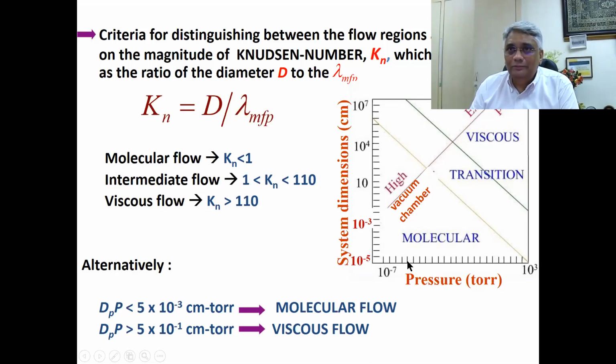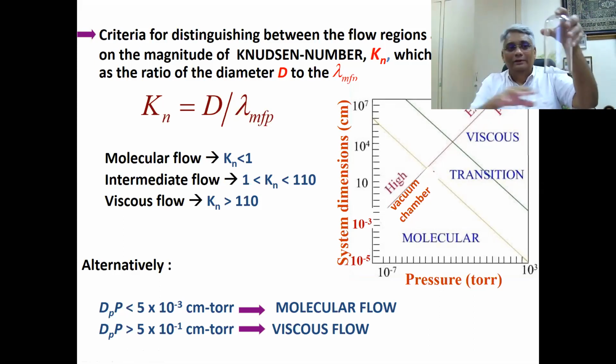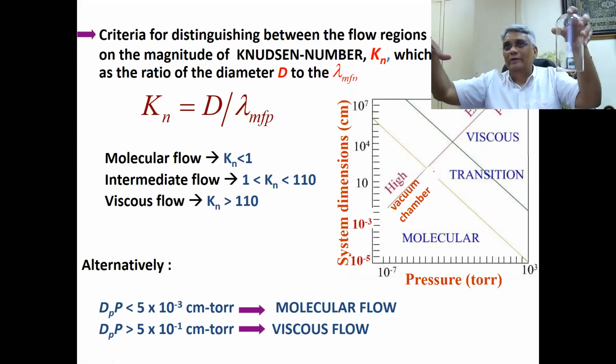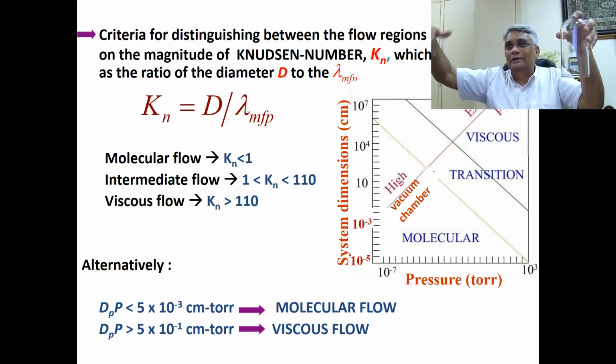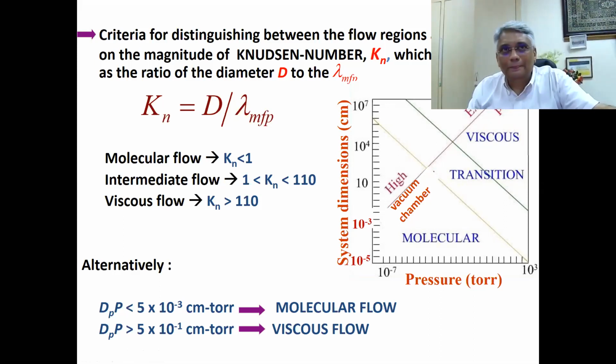And pressure here, low pressure here, high vacuum, and the low vacuum there. So this is the molecular flow regime here, the viscous flow there, and the transition between the molecular and viscous regimes. So it's easy to understand. This is where the chamber is, right? Molecular flow, you want molecular flow here, and as you remove gas molecules and convey it to the ambient, this is happening through all those, the tubing and the vacuum pump. So on the pump side, you always have the viscous flow. It doesn't matter, but what I want is the molecular flow here.